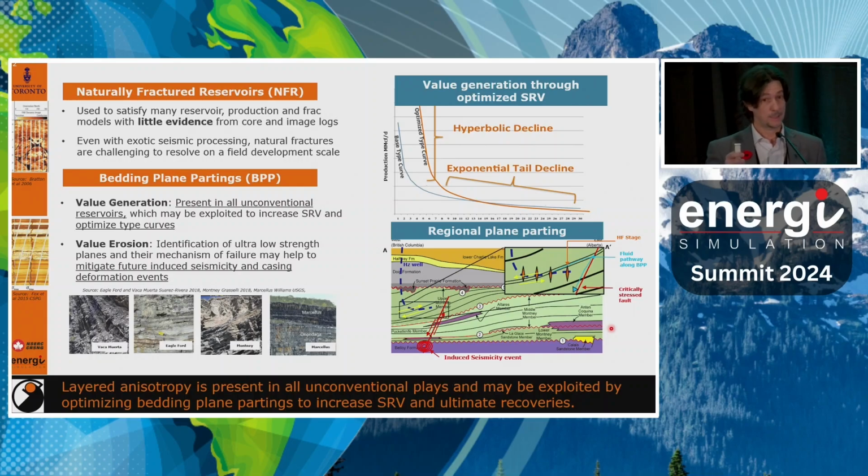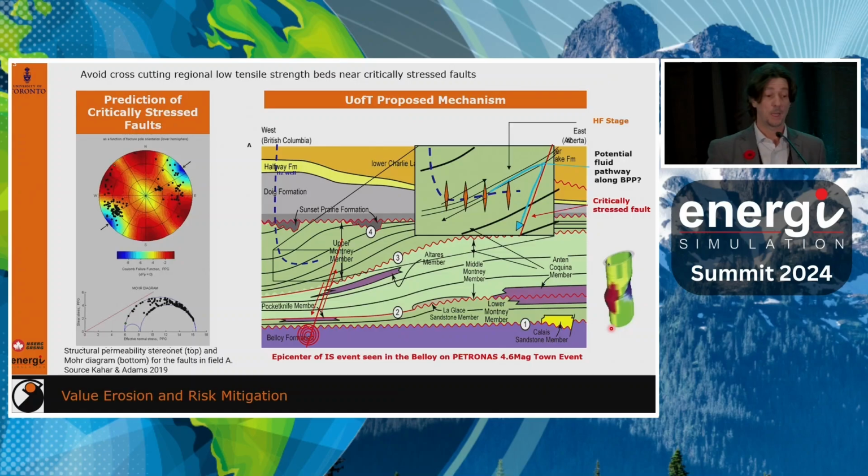Because, I cite again Adi, it is the curious case of fractures. Those fractures might help in mixing CO2, but might also become highways for fluids to move very fast, very far away. And potentially they could migrate the fluid from the well or the area that you are trying to fracture up to maybe a critical stress fault that could trigger a large event.